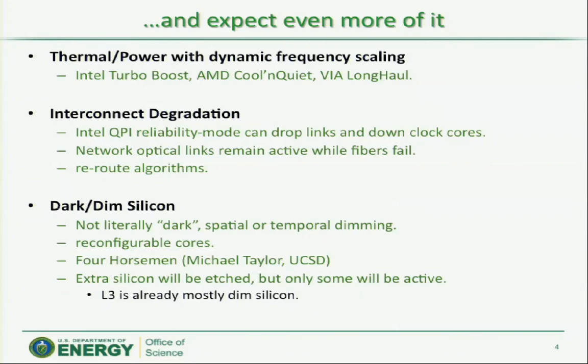And AMD has this, the chipset that's next to your chipset, so your memory bus has this going on, the chips that go to your DRAM have this going on, your DRAMs have this process going on. And then your interconnect, so your on-chip interconnect can do downclocking. So if the interconnect, if QPI is going too slow, then it's going to start downclocking your cores.